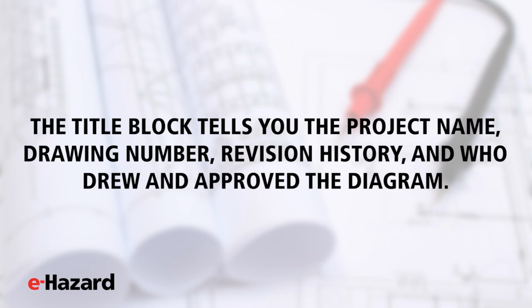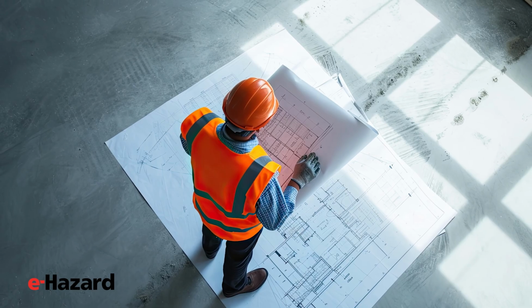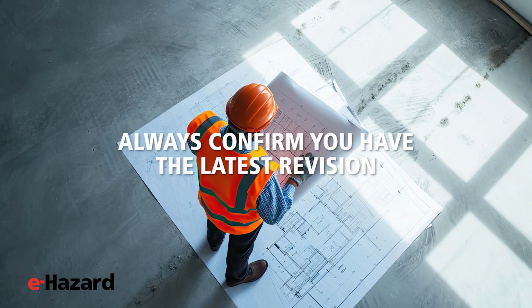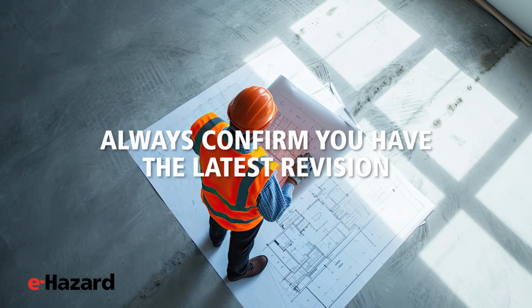The title block tells you the project name, drawing number, revision history, and who drew and approved the diagram. If you're working from a revision that's not current, you could be looking at outdated information. Always confirm you have the latest revision.